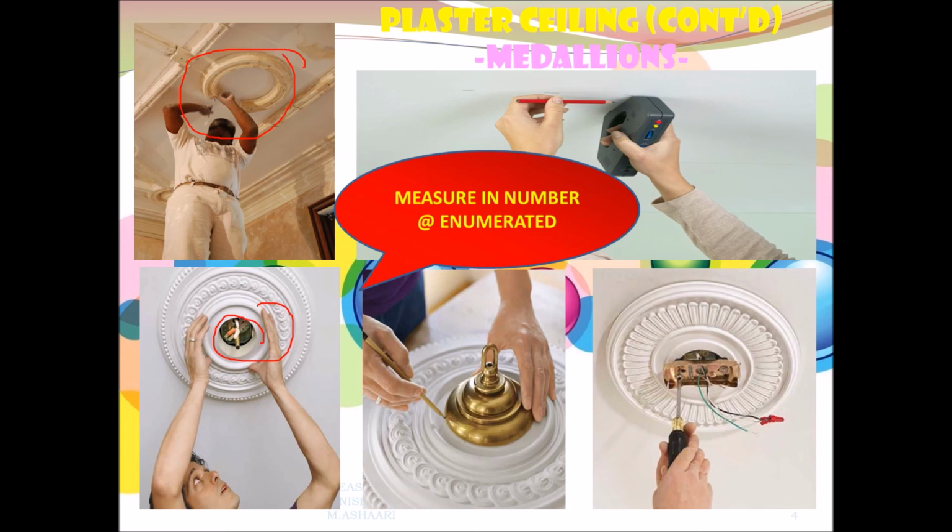There will be no deduction to be considered when you install this, because this is normally less than 0.5 meter square. So if the opening is less than 0.5 meter square, as you see under S.1, there will be no deduction needed for the installation of the fitting.